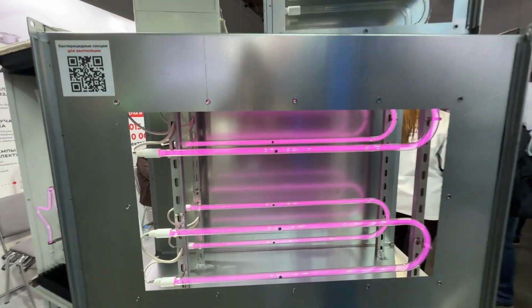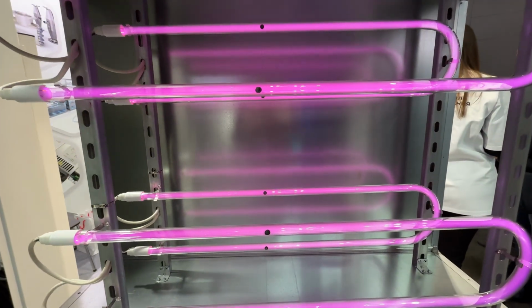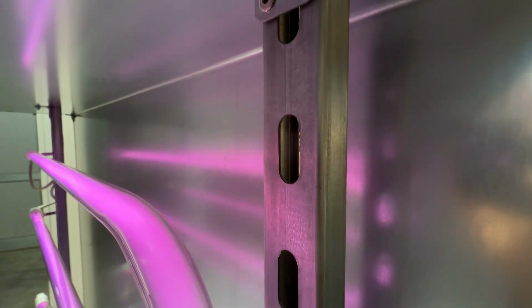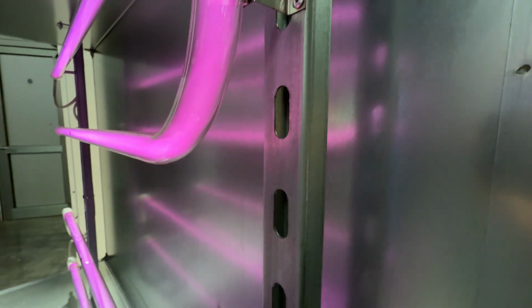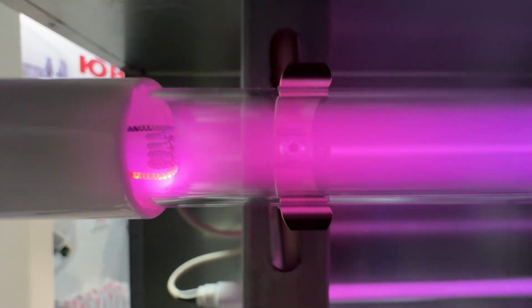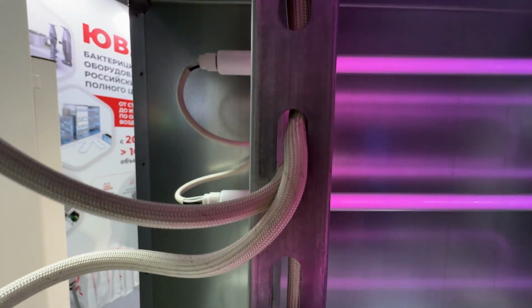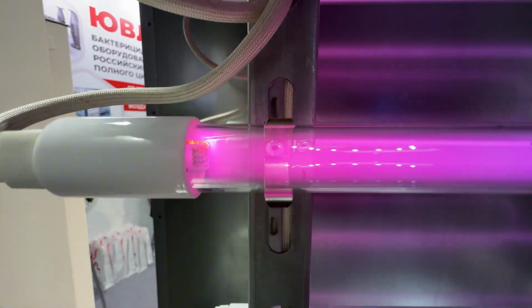The unit consists of a rectangular housing with lamp holders. The holders are fitted with bactericidal amalgam ultraviolet lamps specifically designed for airborne applications. Their spectral characteristics and thermal regime ensure stable radiation intensity despite fluctuations in temperature and humidity, preventing degradation of the UV radiation dose. The number of lamps depends on the required total radiation power and the type of room for which the selection is being made.